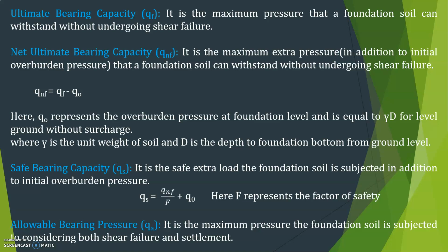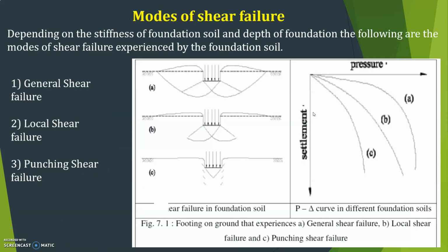So these are some of the important terms you should know while studying in detail about bearing capacity, and also these are important while solving the numericals. Okay, now let us see what are the different types of modes of shear failure. Depending on the stiffness of foundation soil and depth of foundation, the following are the modes of shear failure experienced by the foundation soil.